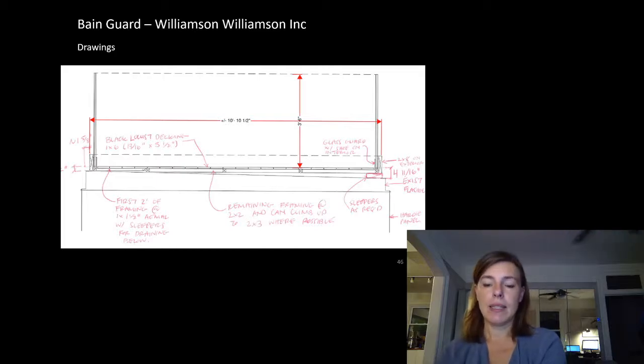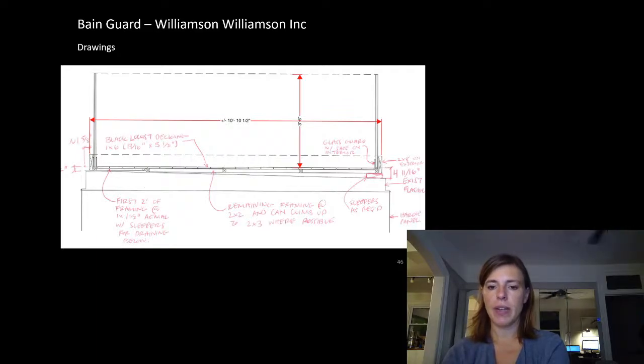The problem is, and this happens a lot, one of the biggest issues for structural rot in wood is piercings in the roof membrane. It tends to be one of the biggest places for flaws in a building. So anything you can do to not pierce a membrane is exactly what you need to do.